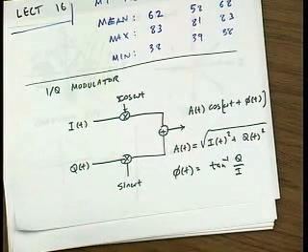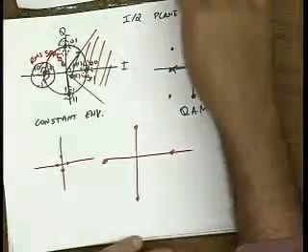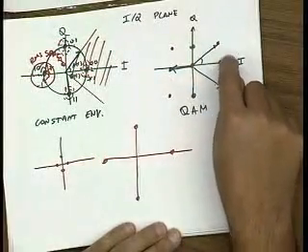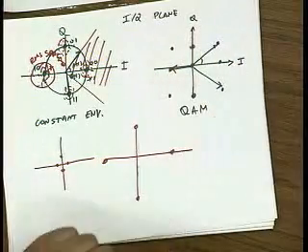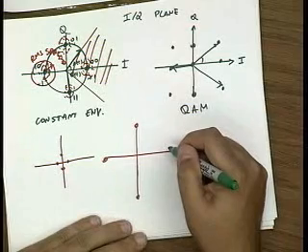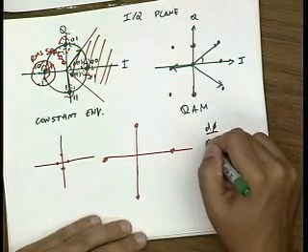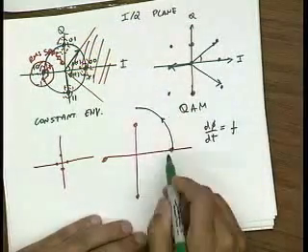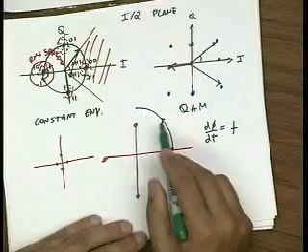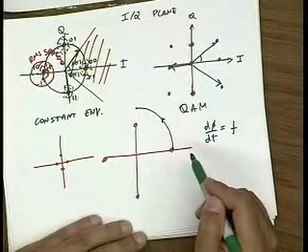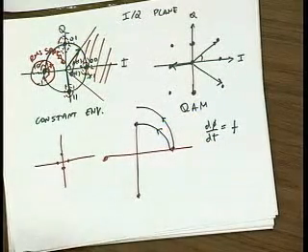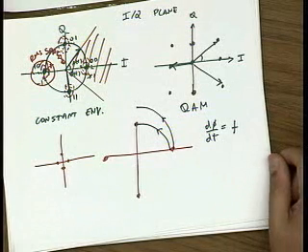Yes? Can you elaborate on the frequency modulation on this diagram? Sure. So basically, if I constantly change my phase, so if instead of sending discrete points, I send motion right along this circle, that corresponds to frequency modulation, right? So if I take d phi dt, if I move constantly along this circle, that corresponds to a frequency. It's the rate at which I change the phase, which is the frequency. If I move faster, that corresponds to a higher frequency. Okay, good question. Any other questions?